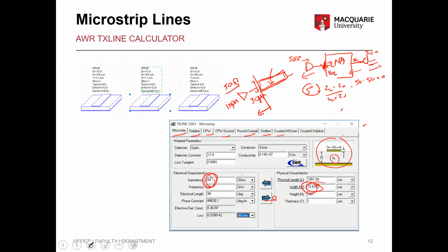In an LNA you have two stages, say stage 1 and stage 2, and then you have the input, and then some sort of matching circuit. Stage 1 can be a transistor, and its input will have a certain impedance. Say it can be a complex number, so it could be, say, 20 plus 30j. I don't know whether it's right or wrong, but then your matching circuit will transform this 50 ohm to that impedance here.